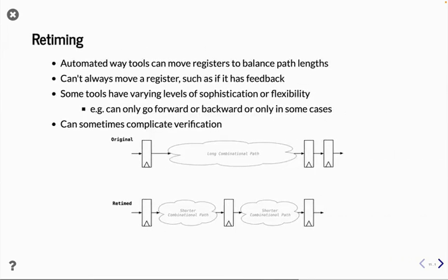And that's the next slide, retiming. So this is technology that was developed originally in the 80s and became productized in the 90s. I believe this actually was Charles Leiserson's PhD thesis, where he actually won the ACM Doctoral Dissertation Award. And so he figured out, you know what, why not have tools move registers around, right? So if I have the semantics of my design such that I have the parallelism and have the registers, usually it's possible to move registers. So he's not adding registers, he's not changing the semantics, he's just moving them around in the design, right?